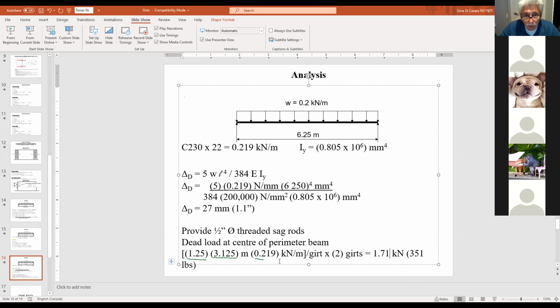But that wouldn't make a big difference because... Oh no, it hardly makes any difference, because our perimeter beams are usually all over designed. Well, they are, and in shear, like you said. And then don't forget, once the wall panels actually get attached to the girts, the wall panels now start supporting the girts, right? So even that can become pretty redundant once the wall panels are in.